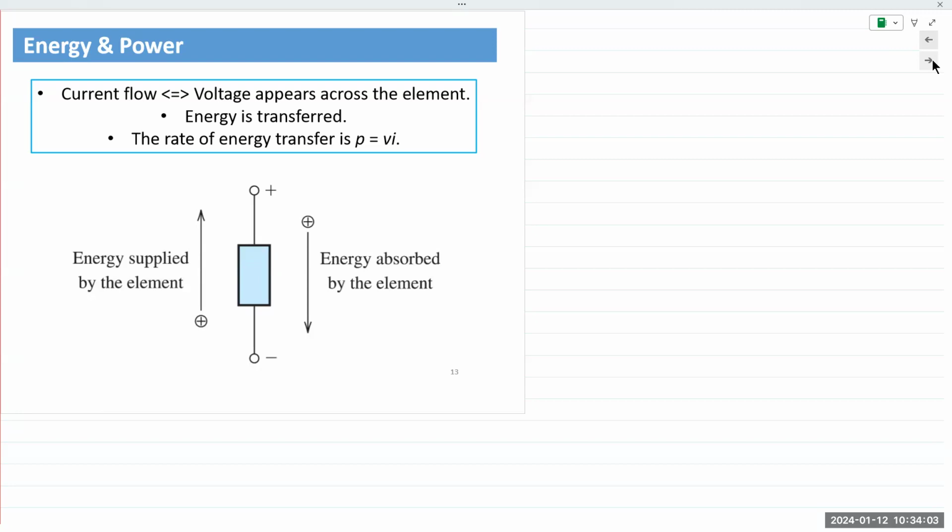That heat could be on the order of nanowatts or even picowatts, 10 raised to minus 9, 10 raised to minus 12. But if you have billions of transistors on one device, which is the case nowadays for most CPUs and microchips, then you multiply that by a billion or a trillion, and each picowatt or nanowatt combines to dissipate energy in the amount of tens of watts.